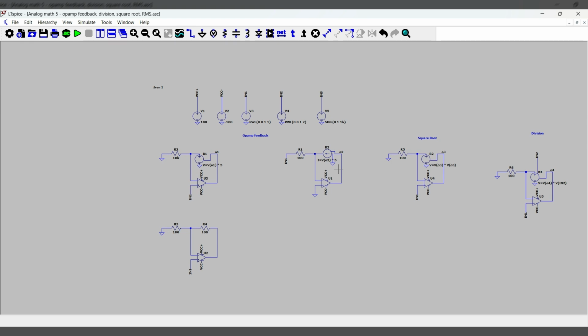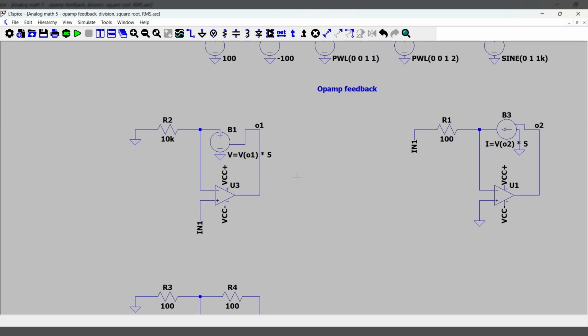For example, if we have a function that created a square, so the input voltage is x and the output voltage is x squared, and we want to create square roots, we can just put the circuit that generates that function into the feedback path of an op amp. And the output would be a square root. So I'll just give you a demonstration of this.